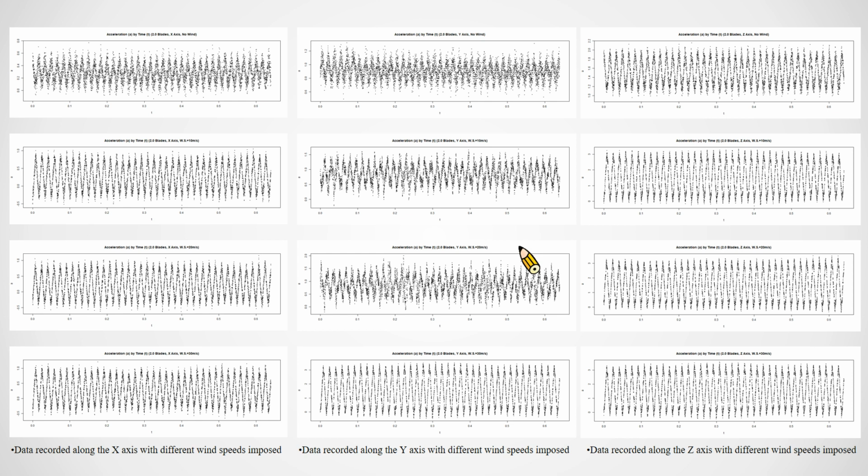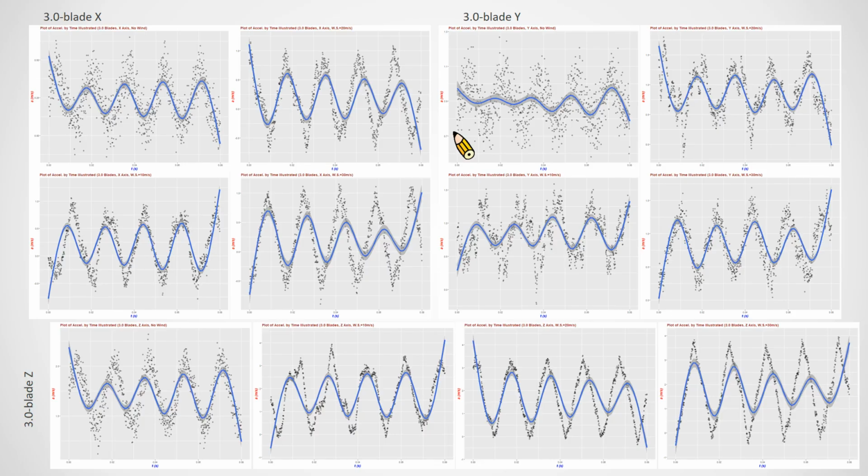And when it comes to the source acceleration signals for the cases where a full blade is missing, which means the case of 2.0 blades, here are the situations. Then we find that using the local regression method for the first 1024 entries of data in each dataset, we can see the smooth line to represent the trend of the data points.